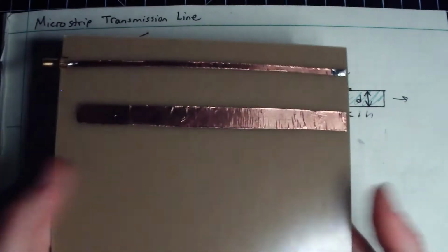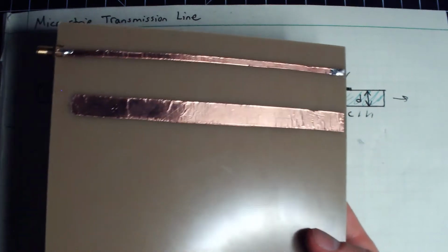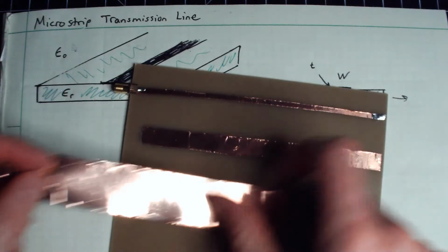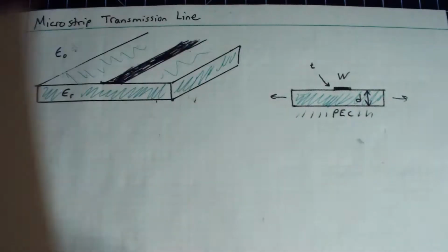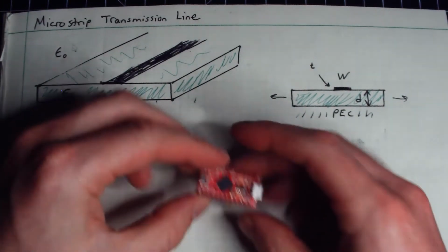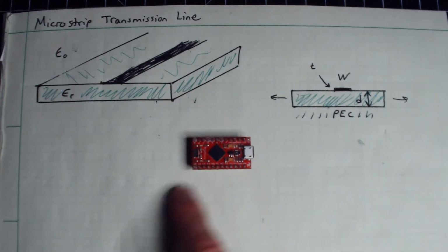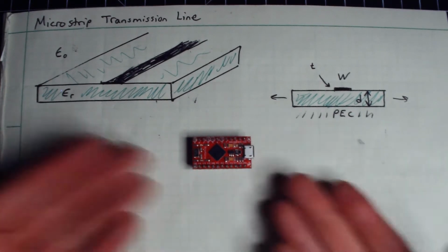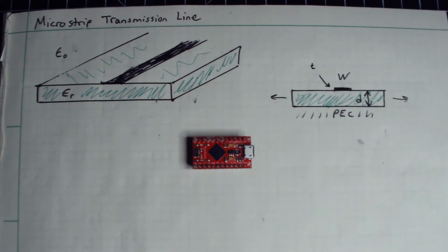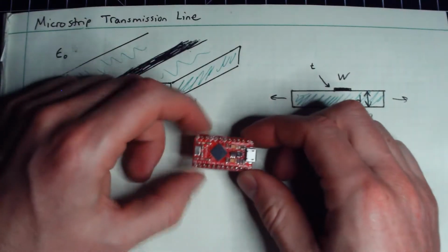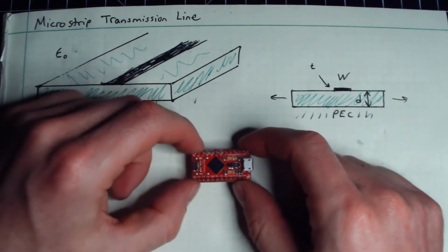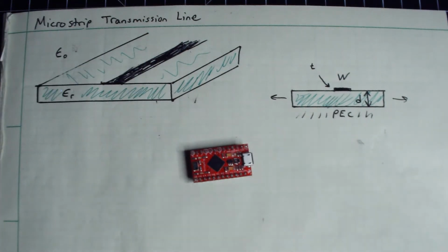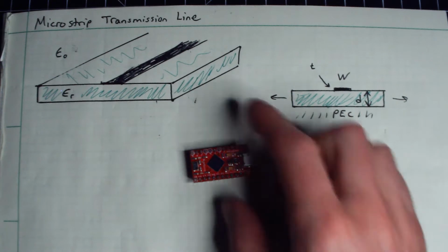Okay, and so it's easy to manufacture. You can buy this stuff off the shelf, and you have copper tape here to deposit your traces. But more broadly speaking, any printed circuit board is very naturally inclined to this sort of geometry, where I could have a piece of copper on the bottom, a little dielectric layer on top of that, and then I can use photolithography to create various traces to route signals, and I can increase or decrease that width there to change the properties of my transmission line.